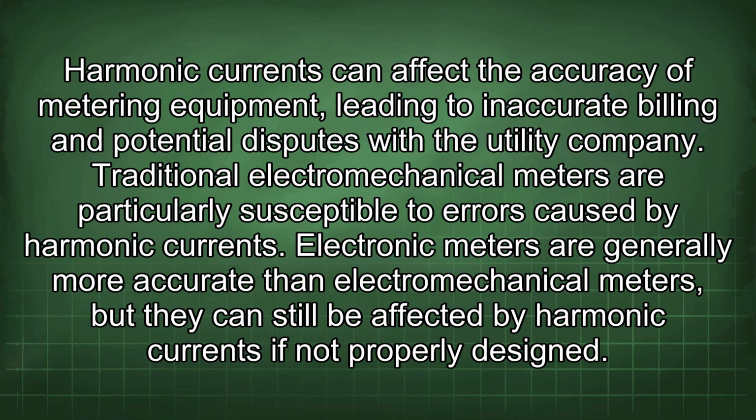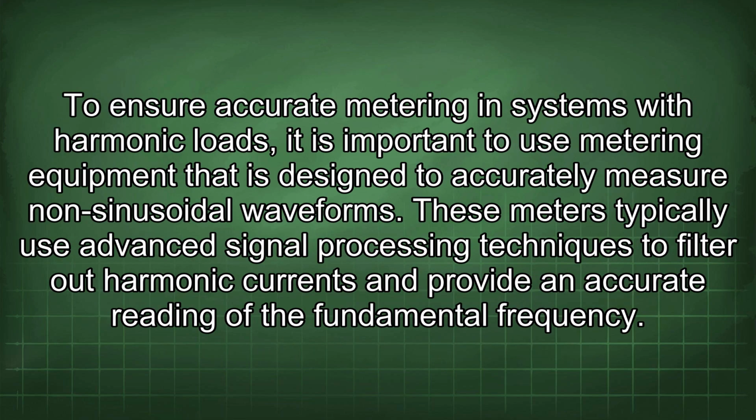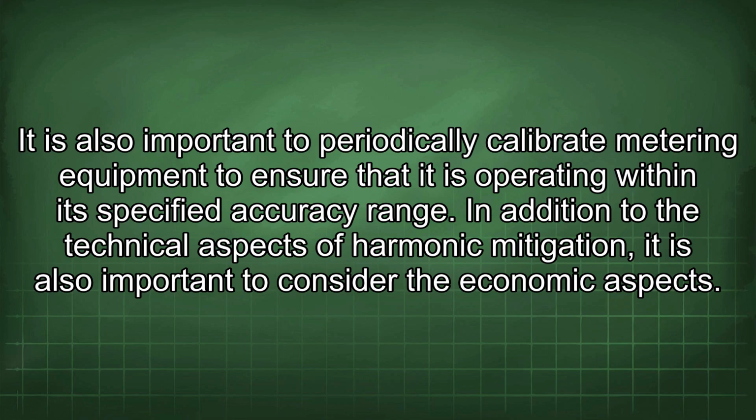properly designed. To ensure accurate metering in systems with harmonic loads, it is important to use metering equipment that is designed to accurately measure non-sinusoidal waveforms. These meters typically use advanced signal processing techniques to filter out harmonic currents and provide an accurate reading of the fundamental frequency. It is also important to periodically calibrate metering equipment to ensure that it is operating within its specified